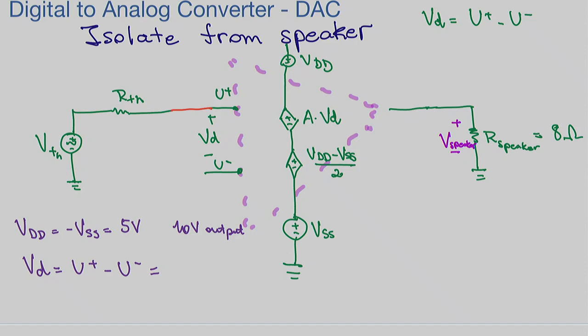That would mean that we would be connecting this voltage here to 0. But since we are comparing things and we want to have some sort of reference, it would be also useful to connect our U minus to a reference voltage source. A voltage source that we know. And then we connect that to 0, and I'm going to call this Vref, reference.